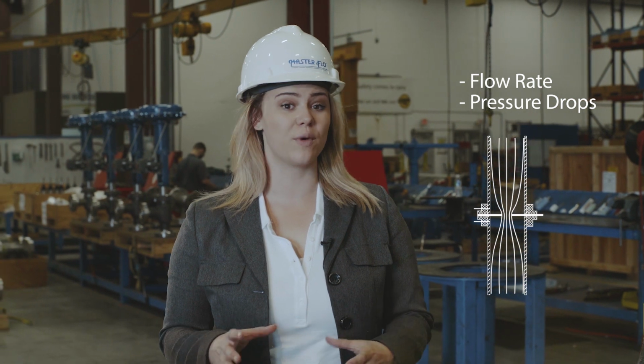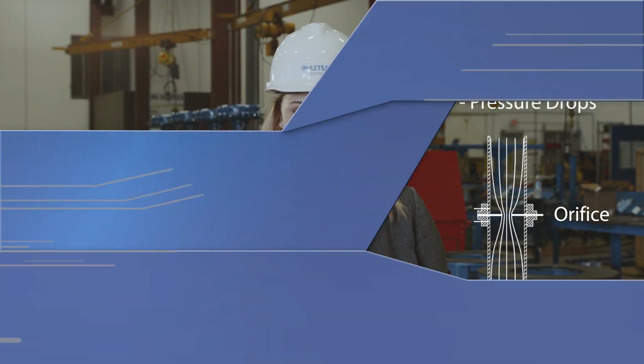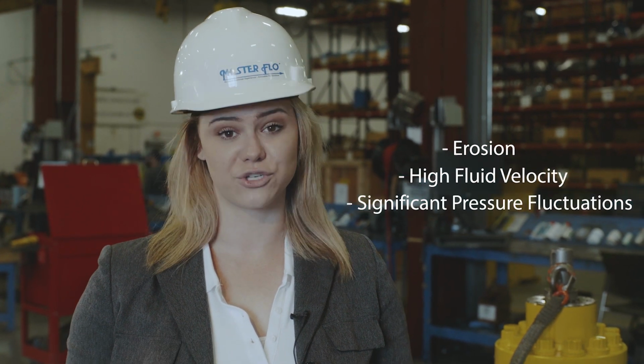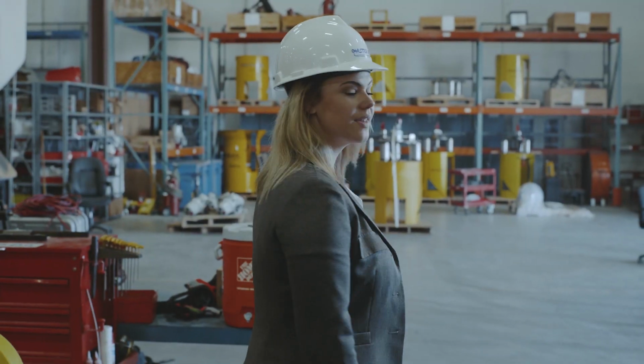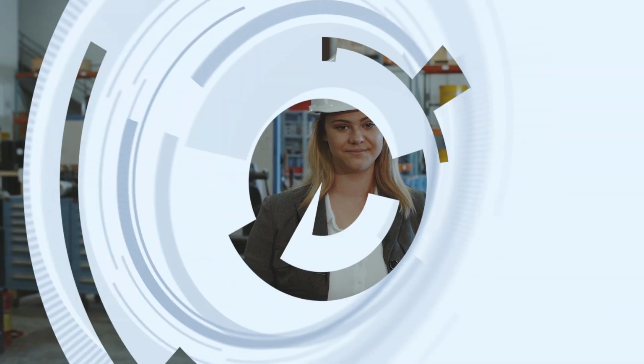Reducing the flow channel with an orifice accelerates fluids, sometimes to sonic speeds. For that reason, the design of a choke valve must consider the effects of erosion, high fluid velocity, and significant pressure changes. Choke valves are categorized by their application, including drilling, injection, and production.